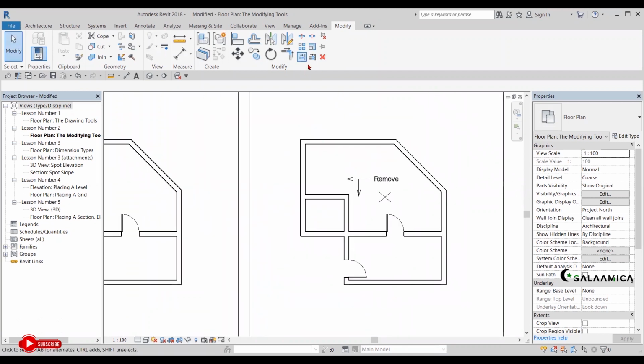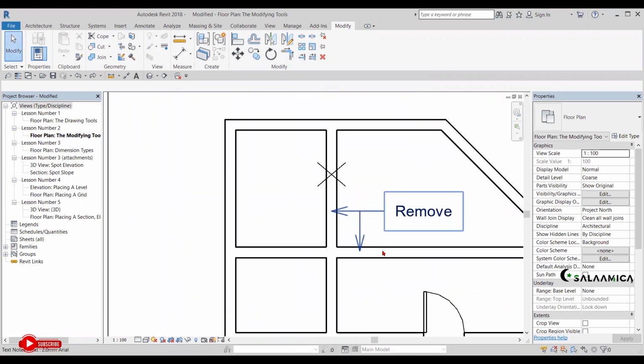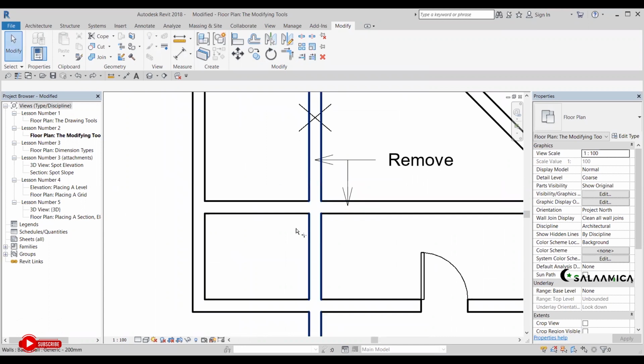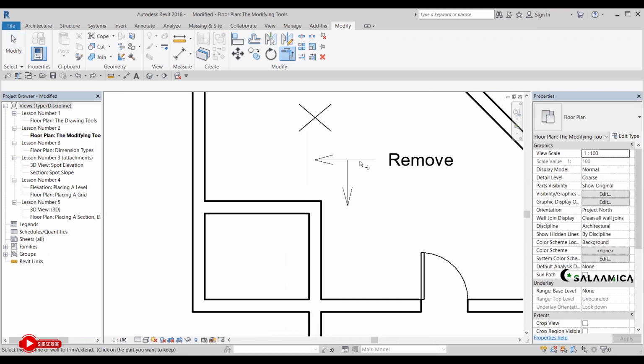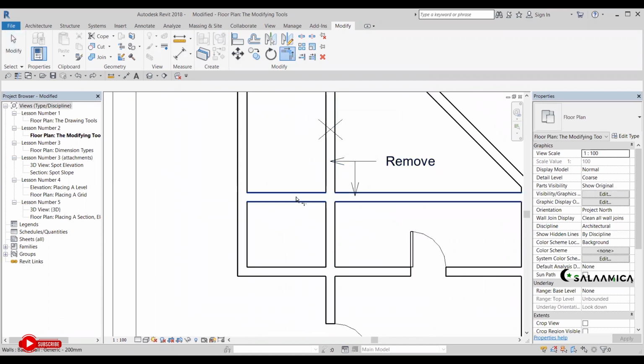So this is just for the sake of the exercise. What do I mean by that? Since you already know what you need from here is to delete this portion, you can also use TR. Job's done. If you're going to undo, press TR, and the job is done.